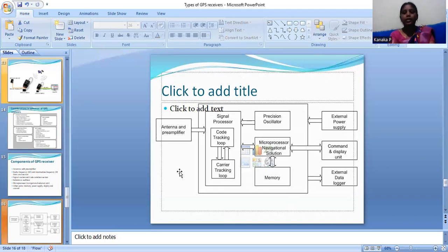The electronic digital theodolite was first introduced in the late 1960s. The instrument has helped to set up the status of modern data collection and processing. So the total station, or electronic tacheometer, is a combination of electronic theodolite, EDM, and microprocessor. EDM means electronic distance measuring device with a memory unit.